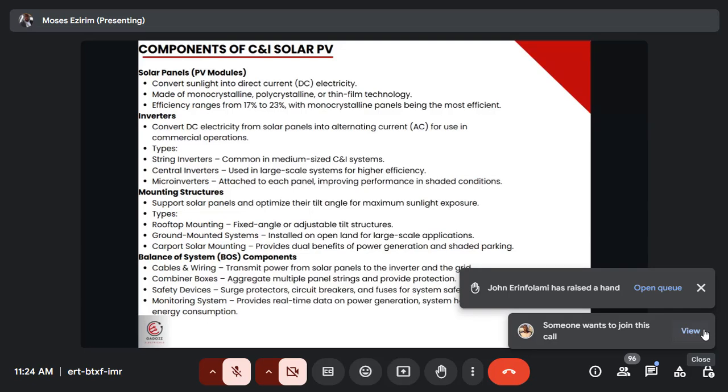So having that in your mind, now if you are monitoring, you realize that one inverter is not generating. If one inverter is not generating, what do you need to do next? You need to move to the site. That's the reason why every C&I company has field guys. The reason why those field guys are there is that once anything is not in place with the system, they proceed to the site to rectify it on the spot. They have an expected time of arrival. Some is 1 hour, some is 2 hours. Rectify it on the spot. There is no need for going and coming.